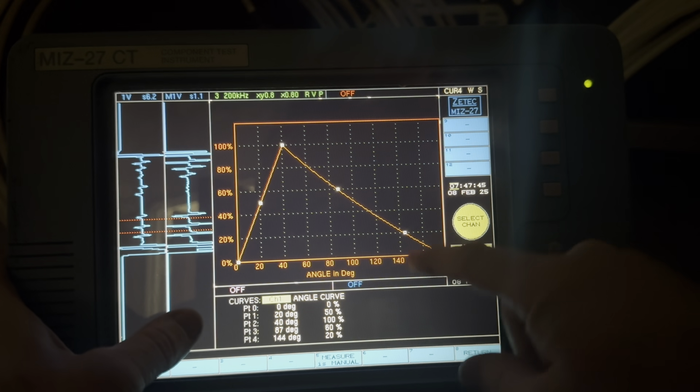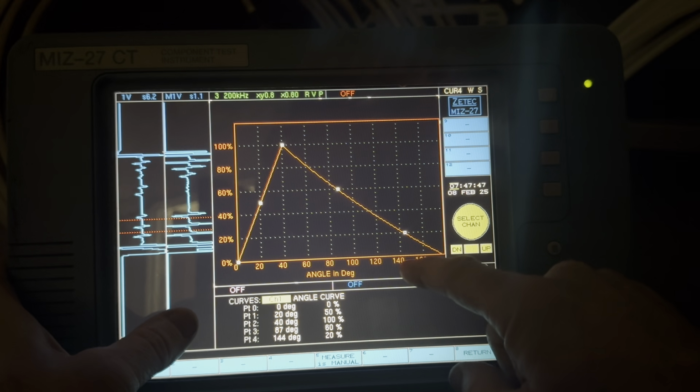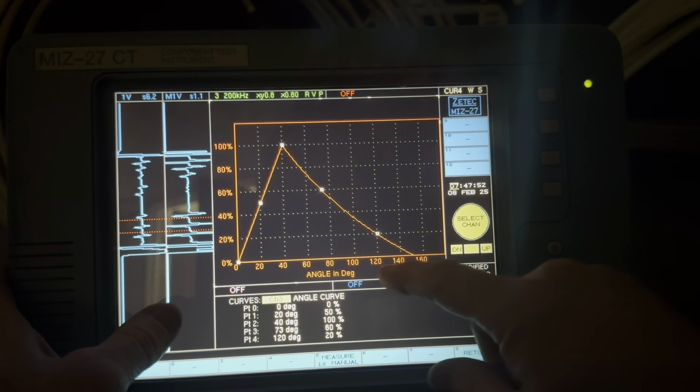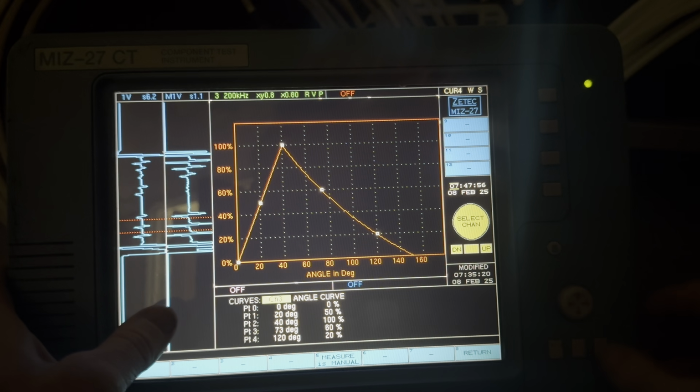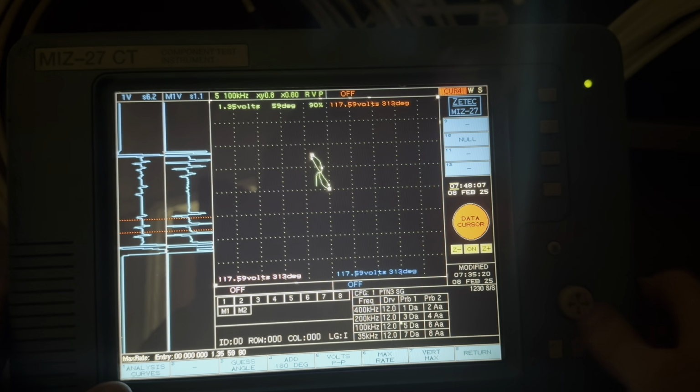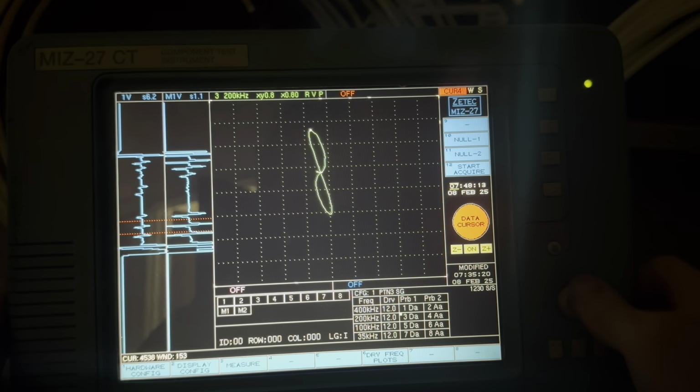Okay, channel 1, the 20% holes are at about 145 degrees. And if you go to channel 3, those same flaws are at about 120 degrees. Now let's go to channel 5. I probably don't have a curve set up. Yeah, when I went to channel 5, you see 4, 5, 6, they all look exactly the same. So I didn't set one up for 5 yet. So we'll do that real quick. So here, okay, that's channel 5. Our 100% is set to 40 already, I know that.